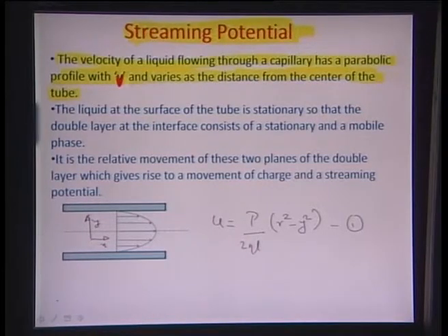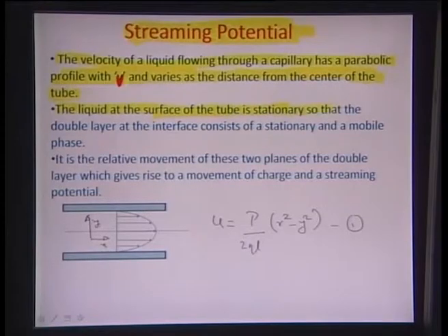So, if you just remember back the various ways and means of predicting the various electrokinetic properties, there can be a case where you give a pressure driven flow, and it creates a set of charges on the walls, or a set of currents, and there is a case when you apply an EMF from outside and it generates a flow. Okay. So, in one case the cause is the EMF, in another case the cause is the flow. So, flow generates EMF inside the channel. The phenomenon is also known as streaming potential.